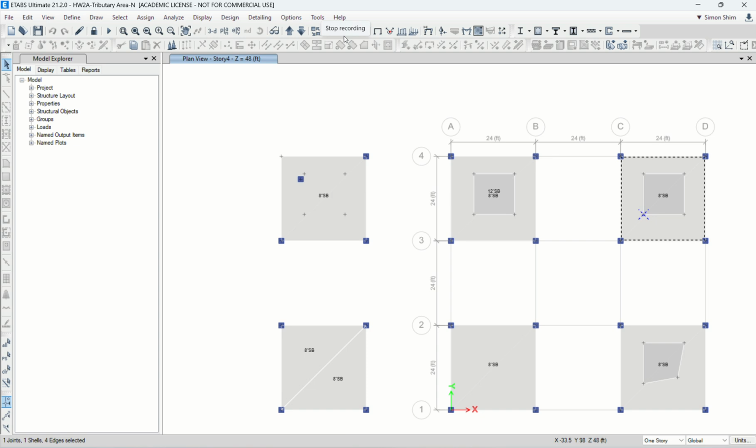We need to be aware of the type of slab elements based upon geometry, square, rectangular versus triangular. But in some buildings, because of heavily complex geometry, we sometimes mix them, because we cannot always use squares or you may end up with tons of mesh elements. So sometimes we have to mix and match, but I want you to just be aware of this.